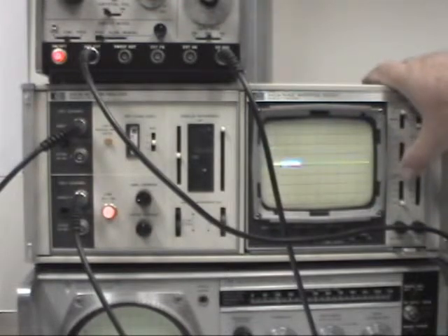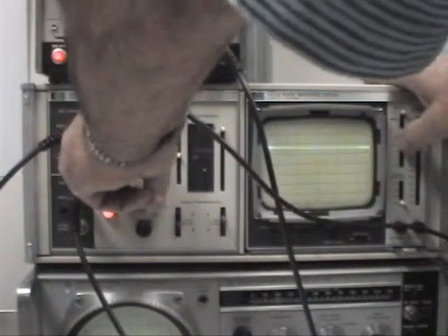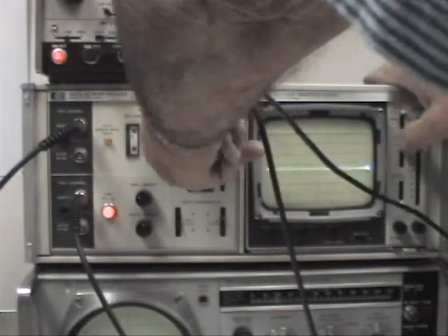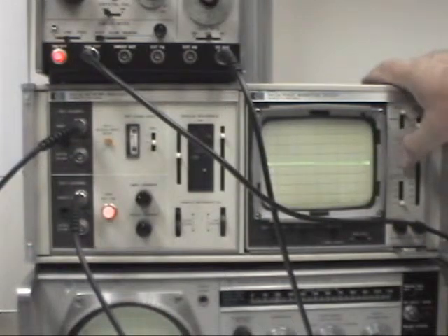We only shift a little over 1.5 divisions when we go down to the quarter dB position. I have an amplitude vernier here I can adjust. I just hit right at the bottom of its range, so I'm going to take out some more with the 1 dB position, and there it stays put, switching between ranges.